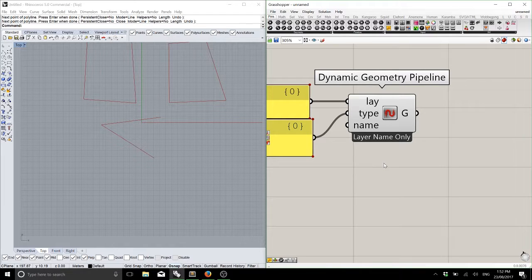The key thing is, if you start writing this into your logic, so if you know that you can't turn that into a floor slab because it's open, but you're working with someone who isn't necessarily the brightest tool on the shelf, and that happens a lot, and they don't really care or understand that lines can be closed or open, then it's worth putting this system in so that you don't have to constantly check their work, okay?